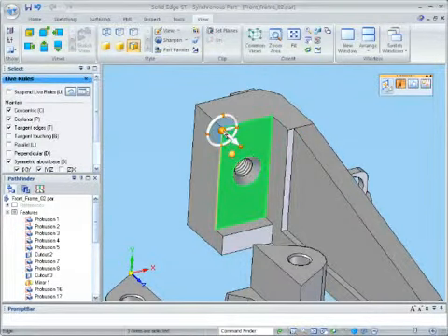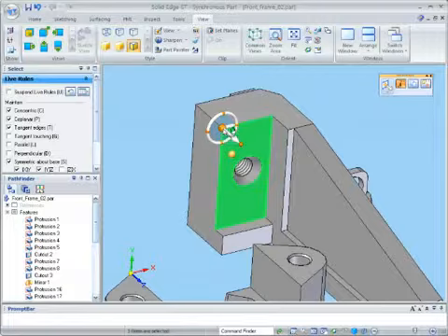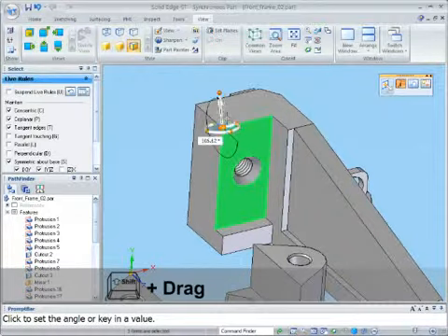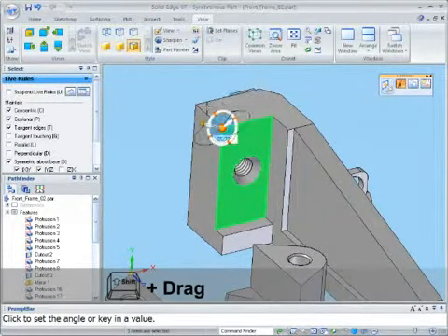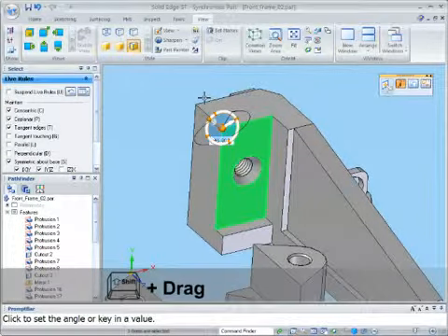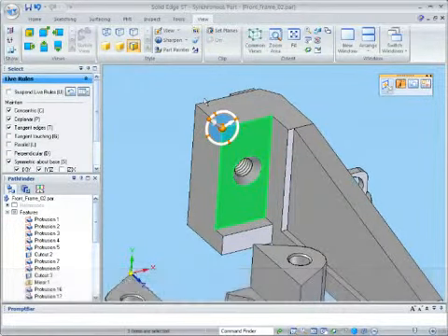The steering wheel can also be reorientated in all X, Y and Z directions. With the steering wheel in position, you can shift-drag the primary and secondary bearings. After setting the first angle, drag again in an adjacent direction to set up a compound angle.